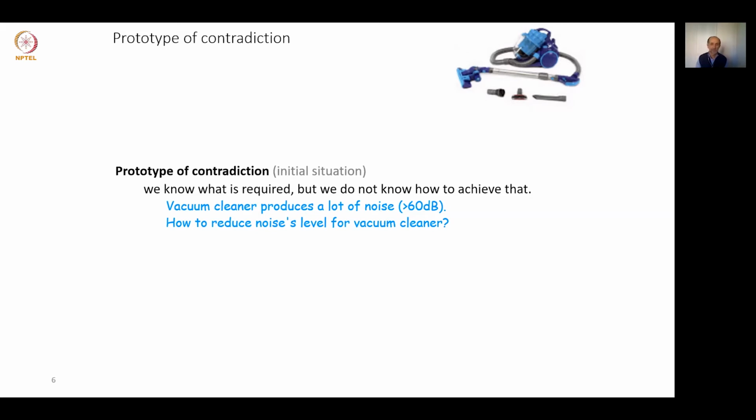Such a situation we can describe as a contradiction. In the body of TRIZ, they name it a technical contradiction. This situation can be represented in words like: if there are few damping materials, then the power of sucking is good, so our vacuum cleaner is very efficient, but the noise level is high. This is most vacuum cleaners that you can find on the market. But if damping materials are added, do you remember what the experienced engineers suggested? You need to reduce noise, add damping materials.